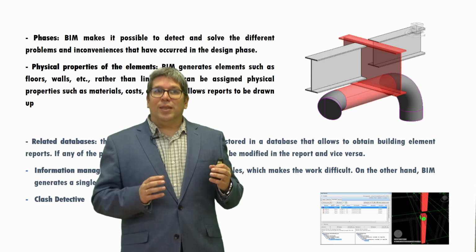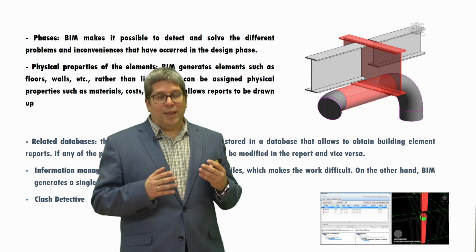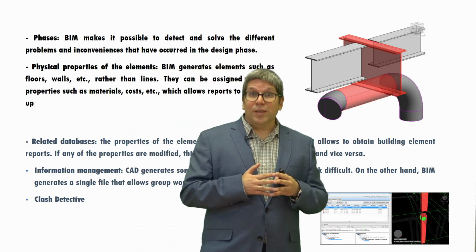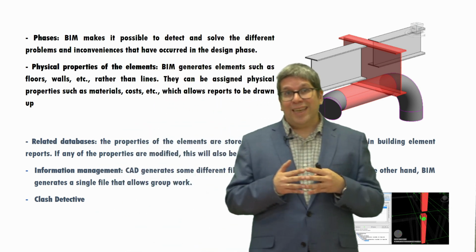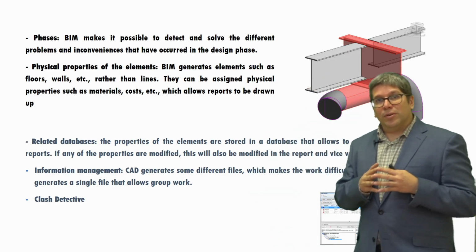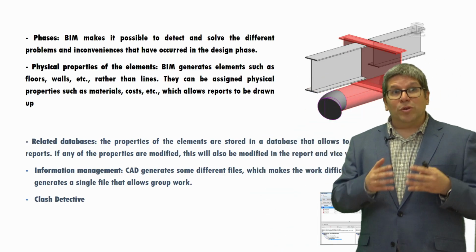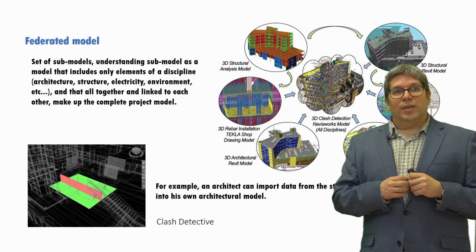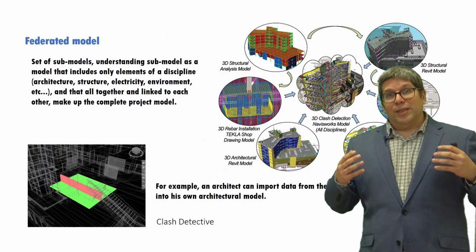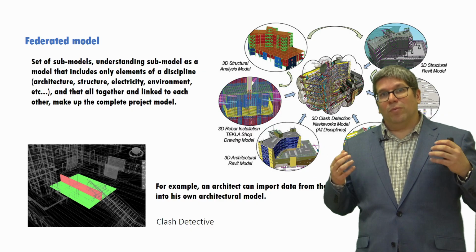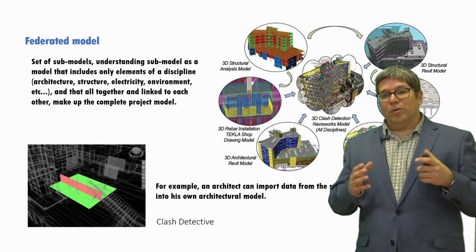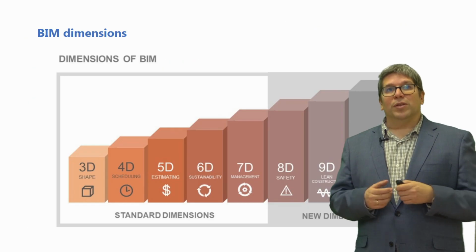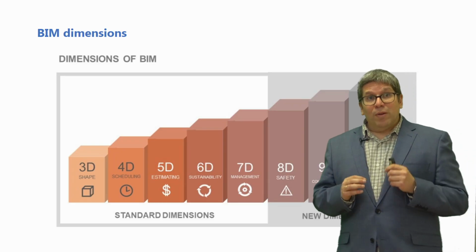With this advantage and other ones, for example, clash detection, in which I can collapse two disciplines and see if there is any interaction that I should consider during the design phase, I can reduce a lot of errors typical in the conventional projects. So the federated model means that the collaborative way of working can be all together working in the same model so that we can reduce these errors. And once we have the 3D model,